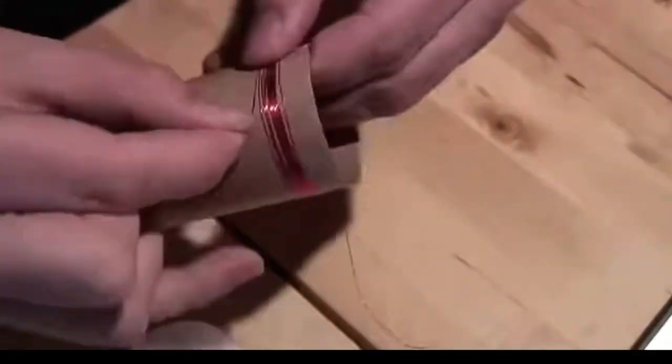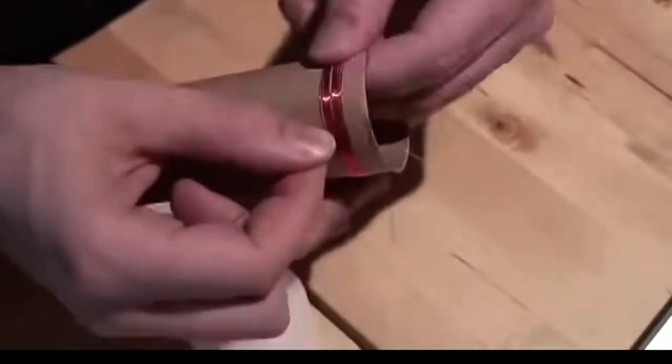Alright, let's make it. For the coil, I'm using magnet wire. That's because it's got a non-conductive coating. GIs in the field would have found stuff like this in motors, or they could have just used regular wire and coated it with varnish. You can attach it with tape before you wind it up, or put a hole in it and tie it on. That'll keep it from slipping as you wind it up.